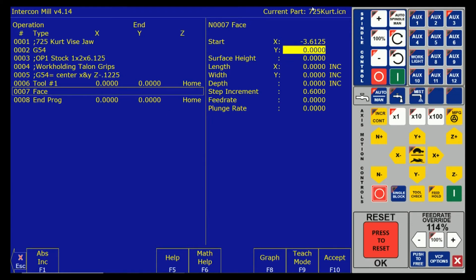As a general rule of thumb, we do not want to engage our cutters radially more than 2/3 of the cutter diameter because the cutter needs to deflect in a direction. So you never want 100% cutter engagement. So here, I'm going to go positive 1 inch in Y. So that is just a starting point in X and Y.